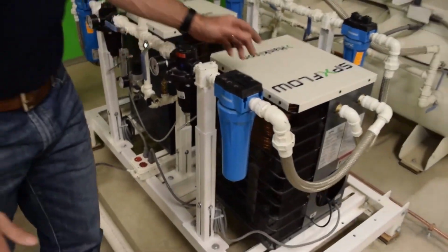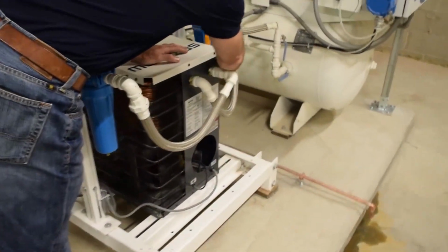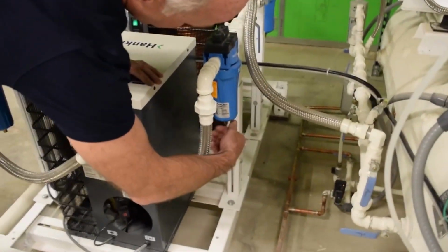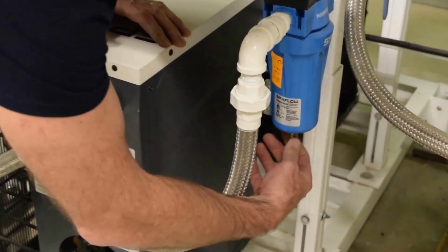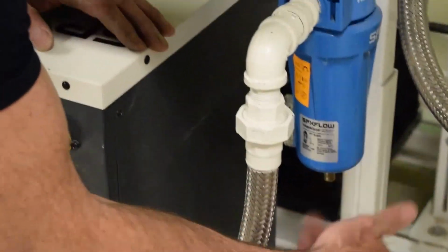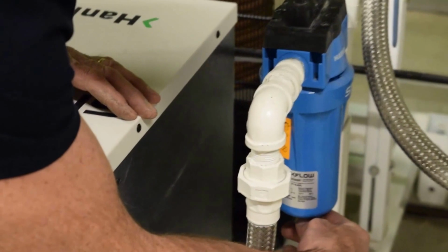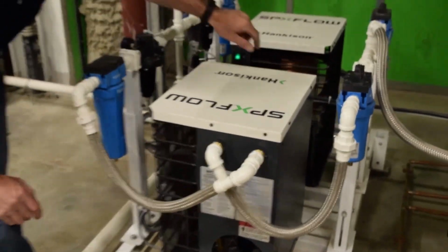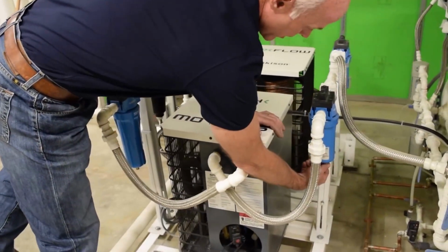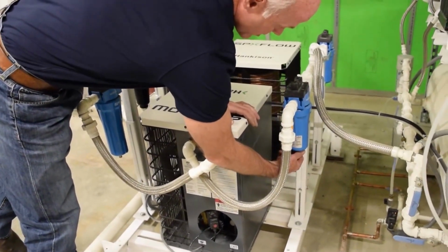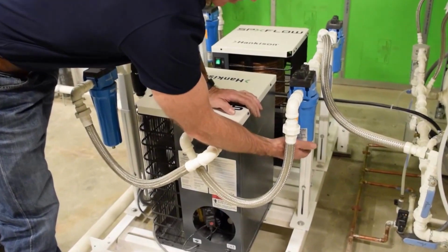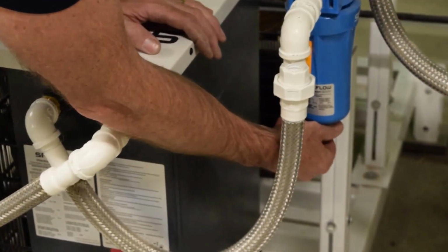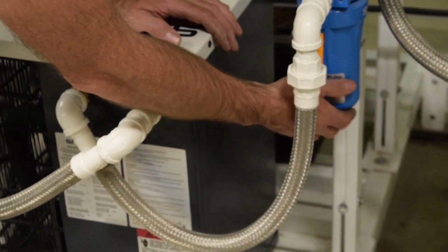On a weekly cycle at a minimum, I would open up this orifice on the dryer that's open. This one's not open, but I would open up this one. You turn it clockwise, and you can allow air to bleed out, moisture if there is any, and turn that off. And I do the same on this side on the active dryer, which would be that one. It's a little stiff. You might have to use pliers the first couple times until you loosen it up. But you want to make sure this isn't trapping water, because the only way for the water to get out of there is to manually drain it. And I would say the minimum, check it weekly.